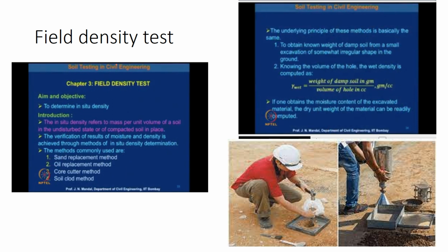Why? Because when it is in the densest condition, the voids are less, so its strength is more. So you'll find it difficult to insert a spoon. In a similar fashion, they compact the soil to the densest with the road rollers. Then they spray water, because water is acting like a friend now.